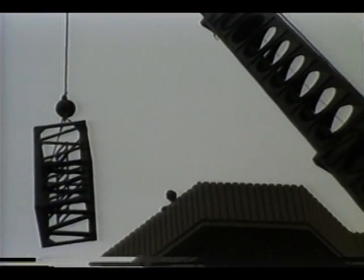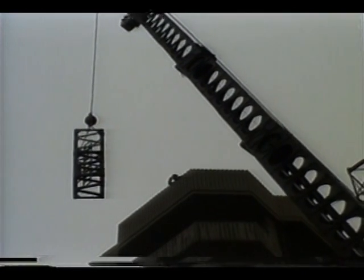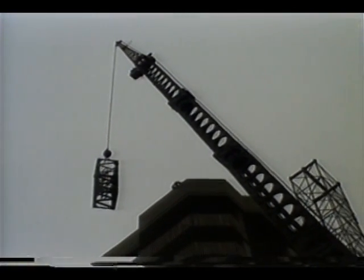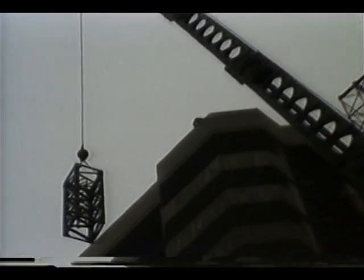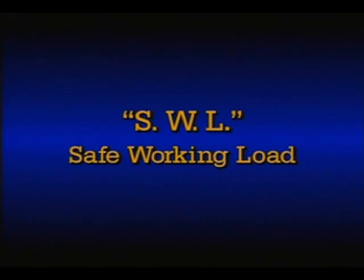Before using wire rope for any hoisting application, you must know the strength of the rope and the magnitude of the load to be applied to it. In connection with these factors, 3 abbreviations are commonly used in rigging. SWL means safe working load. This is the load which can be applied repeatedly without overloading the rope, provided the rope is in good condition.